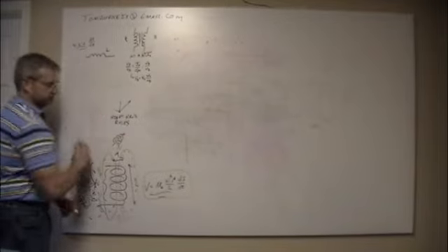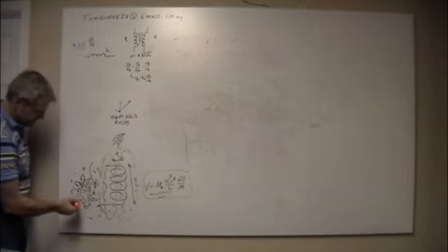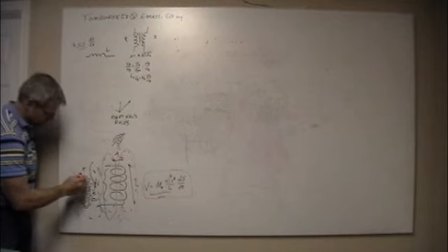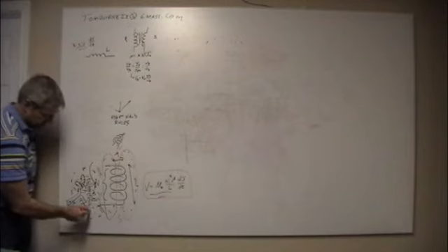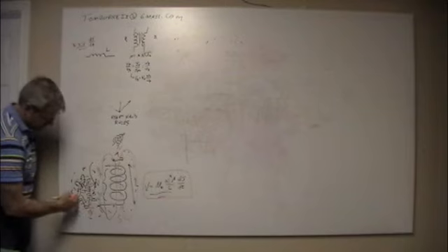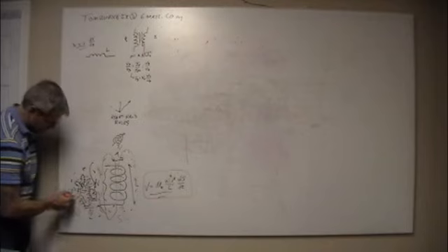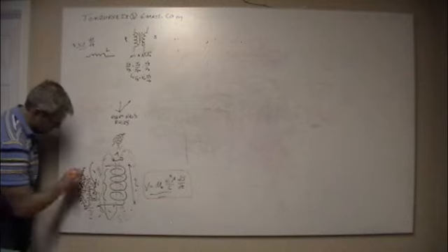So we've gone, and this again is your electric motor. If I've got a magnet here and a magnet there, if this is a north magnet, it's going to repel this pole, and it's going to attract this pole, so it's going to come down like this, and that's going to go up. So that's a north and that's a south.